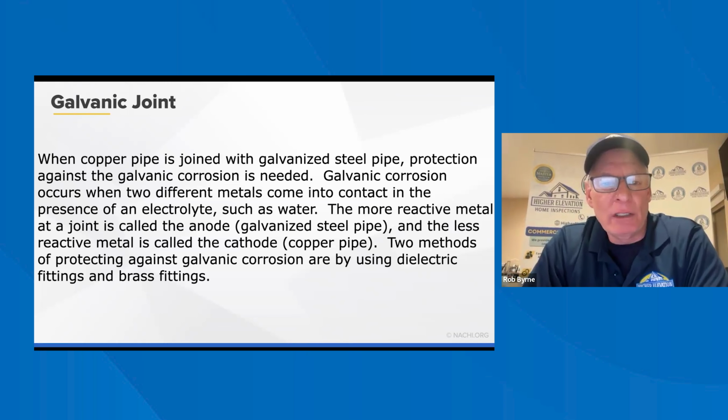Trenching should have solid and continuous load bearing support at the bottom of the trench, forming a bed free of rocks. This is explaining how you would do trenching. Pipe is protected from damage by proper backfill. This is all stuff that's underneath the ground if you're putting in drain lines or water lines.